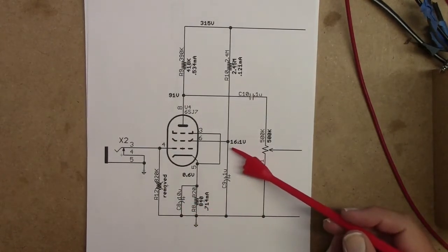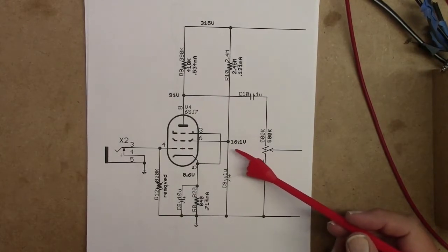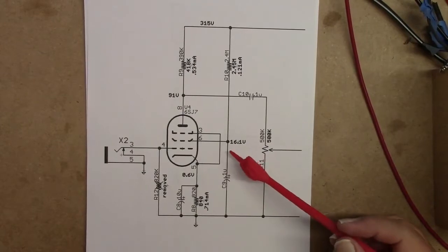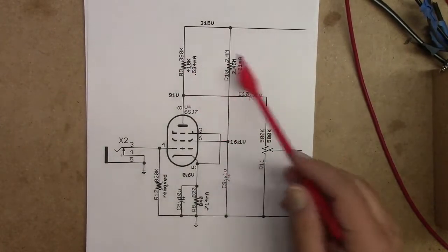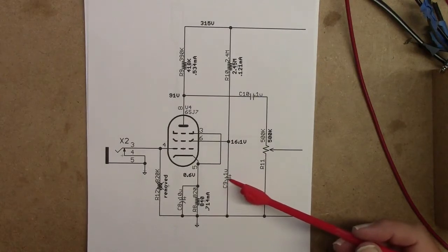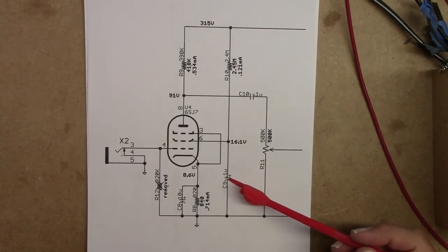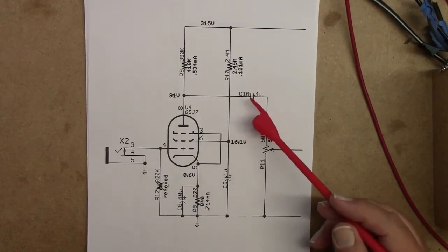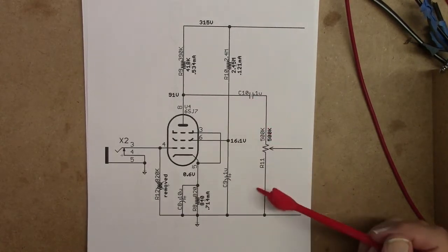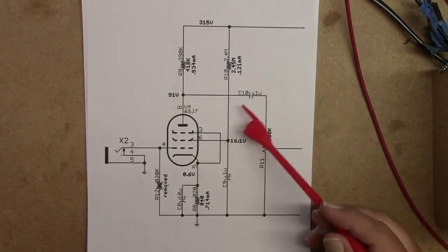And the last time we were measuring things is when I made some mistakes because of the input impedance of my meter. Went through carefully and measured all this again. I also removed this screen bypass capacitor, which is a 0.1, and I checked it, and it is good. And also this 0.1 coupling capacitor over to the volume potentiometer, it is also good.